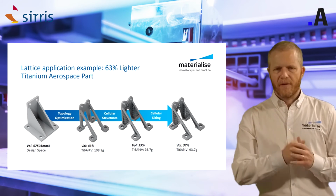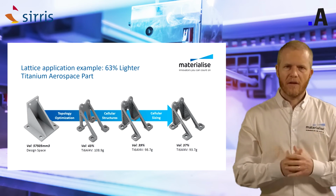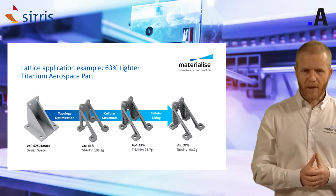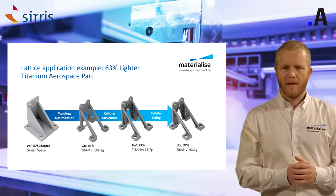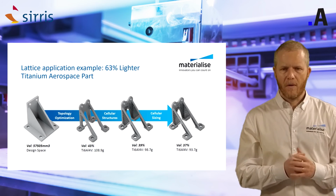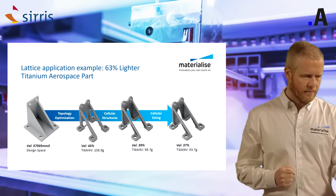So that's the first step, to generate the lattice structure. Then, by changing the thickness of the beams of the lattice structure using FE analysis, we are able to reduce the weight of the part even further, to get to a final weight that is 37% of the initial design space.